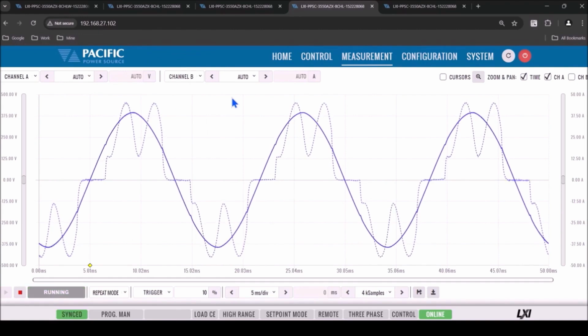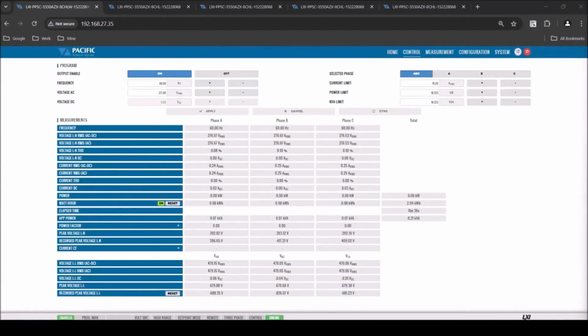Let's now look at a more complex AC load setting using constant current mode and the available transient capability of the AC load. Our next example of the programmable AC load involves the use of the transient capabilities. For this example, we will look at the inverse current transient functions. The power source is still set to 277 volts AC, line to neutral, or 480 volts line to line output as in our previous test, as you can see on the AC source control window. So let's switch to the load screen next.